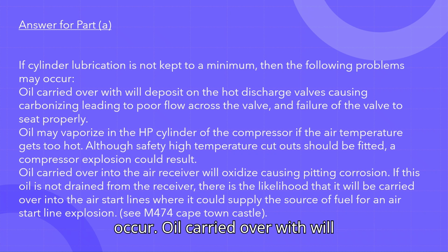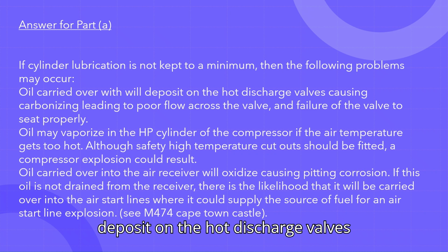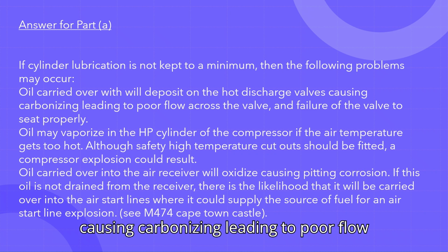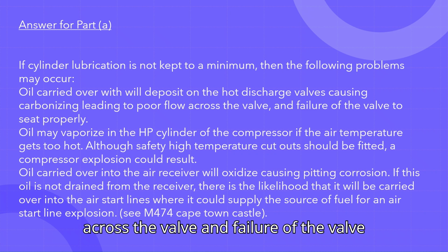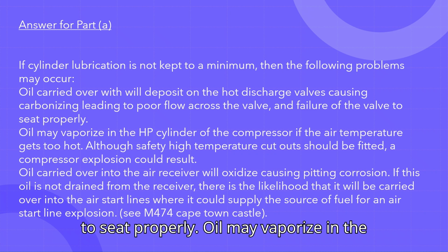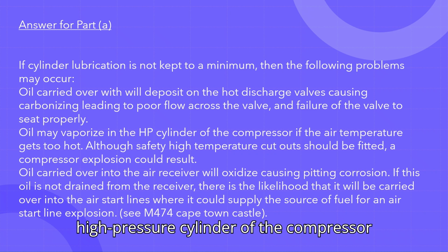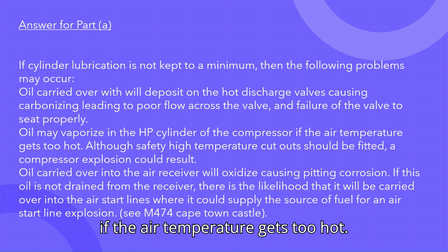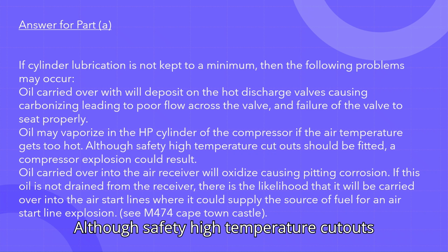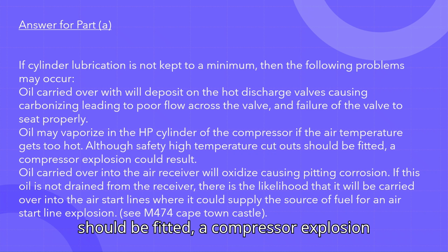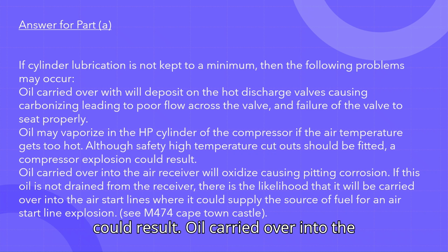Oil carried over will deposit on the hot discharge valves, causing carbonizing, leading to poor flow across the valve, and failure of the valve to seat properly. Oil may vaporize in the high-pressure cylinder of the compressor if the air temperature gets too hot. Although safety high-temperature cutouts should be fitted, a compressor explosion could result.